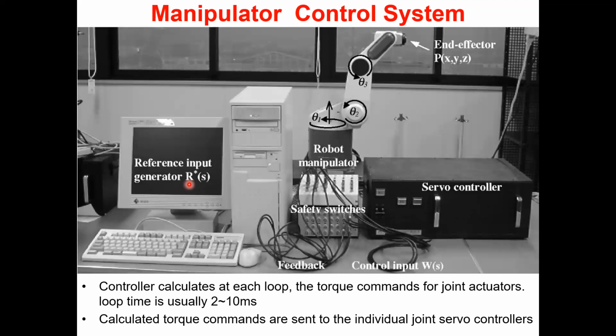So in these 6,000 samples, starting from 0 up to 1 minute, you are going to specify the angle for theta 1, theta 2, theta 3, theta 4, theta 5. What is theta 1, theta 2, theta 3, theta 4, theta 5 at time 0? And after 10 milliseconds, what is theta 1, theta 2, theta 3, theta 4, theta 5? After 20 milliseconds, what is theta 1, theta 2, like that. This is what is called the desired trajectory. Whether the robot is going through that trajectory or not is a separate issue, right? But when you plan your trajectory, you plan it like that.